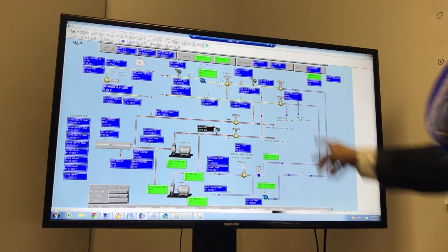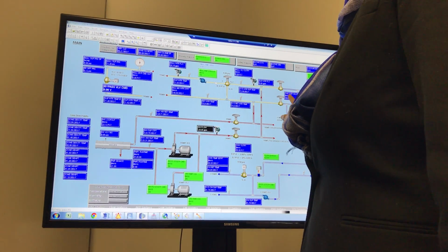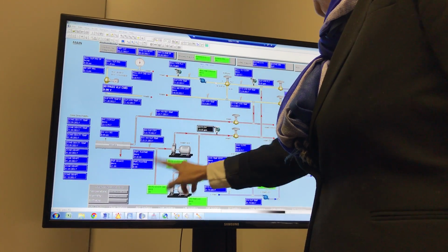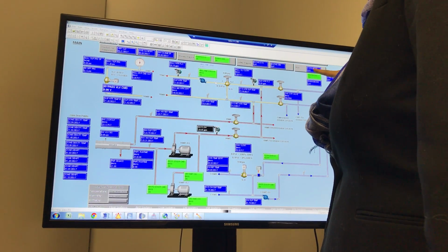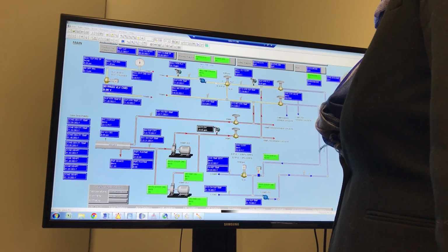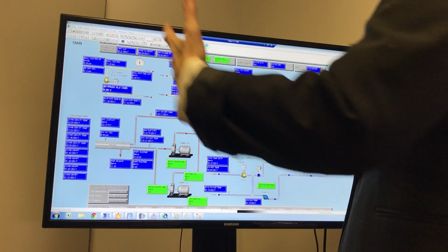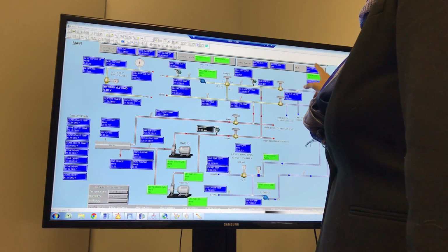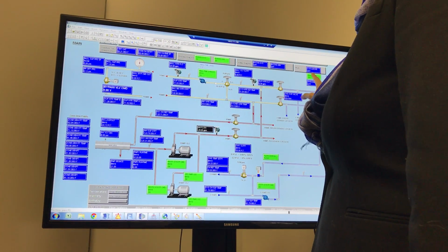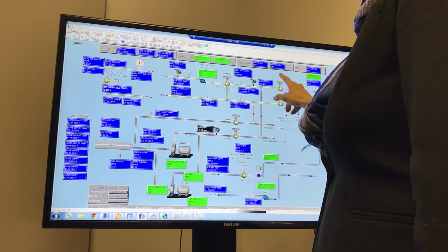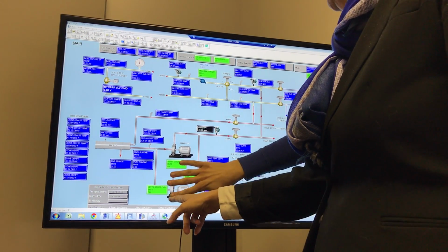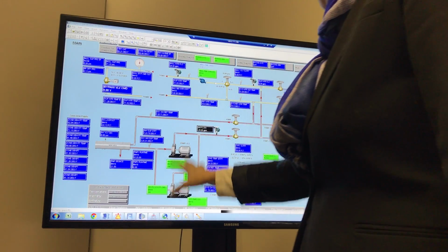So the two things I'm going to be looking for: this word will be the mode, and this will be the main mode. Right now we're in heating, we could be in cooling or we could be in swing. But if there's a problem, it's a warm day, I would need to, number one, look to see if it says heat or cool mode. This is already saying heating or cooling, which is the command for the valves. The pumps are on. The pumps would be off if I was in cooling.